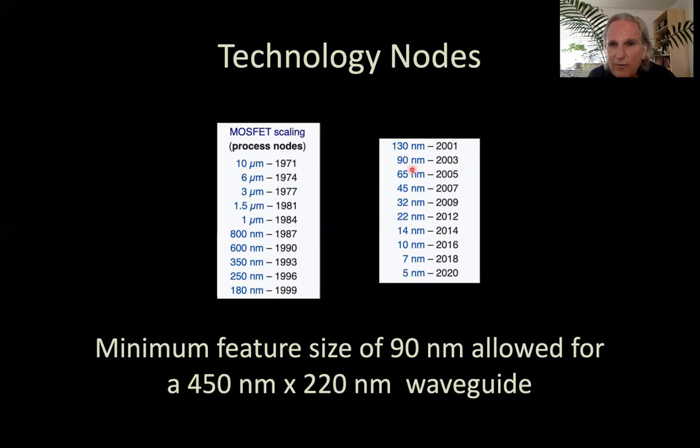By the time we got to 90, they were pretty good. At the 90 nanometer node, you can make good silicon photonics. You couldn't back here. You couldn't make a single mode waveguide. All of a sudden up here, we could take a CMOS foundry, and with that CMOS foundry, we could make silicon photonics. Now there's a 5 nanometer feature size that we've gotten down to.